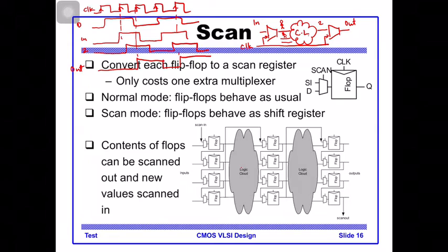Because they want to start at the same time, they have to go through a flip-flop. This flip-flop is known as the register. In your project, you will also have to put a flip-flop for your circuits after the combinational logic cloud to make sure that the circuits all start at the same time.